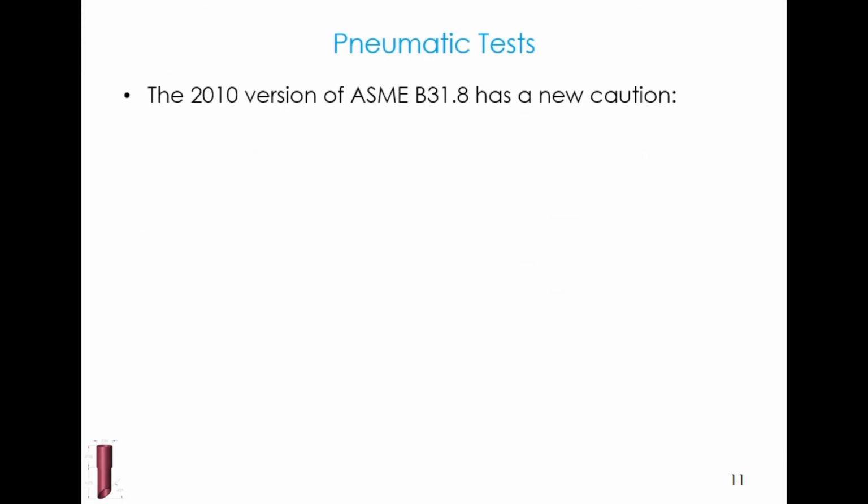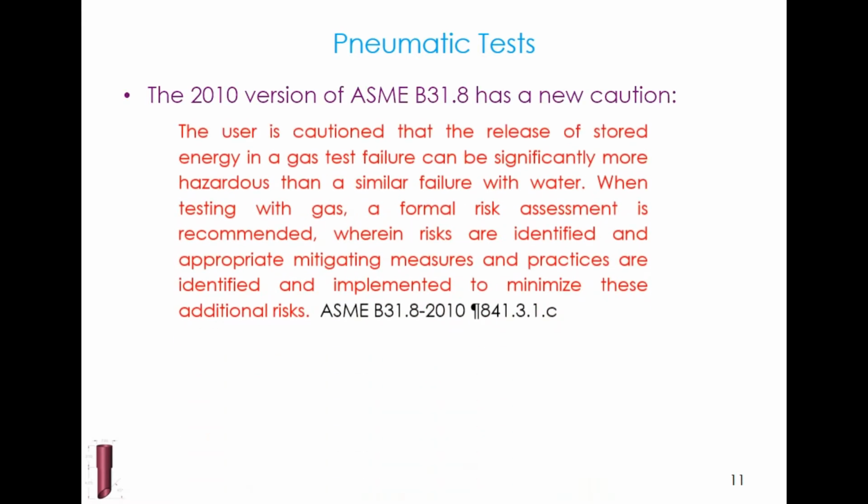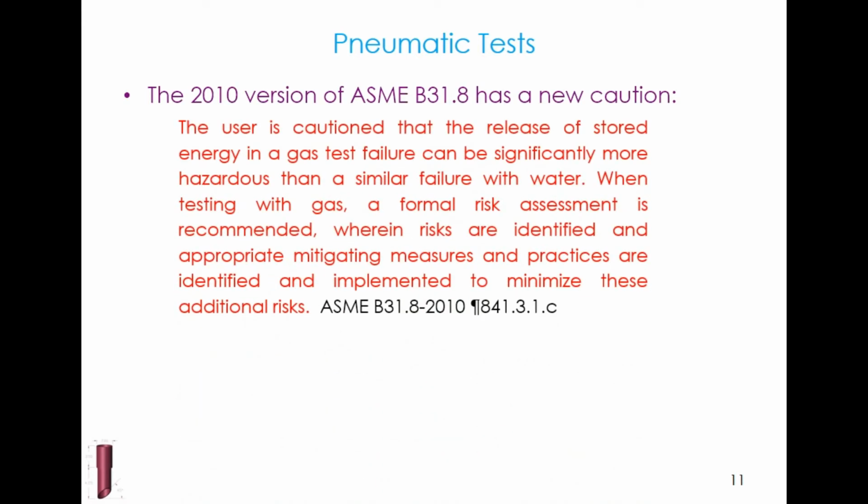The 2010 version of ASME B31.8 has a new caution. They say the user is cautioned that the release of stored energy in a gas test failure can be significantly more hazardous than a similar failure with water. When testing with gas, a formal risk assessment is recommended wherein risks are identified.